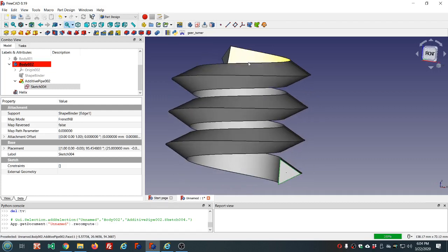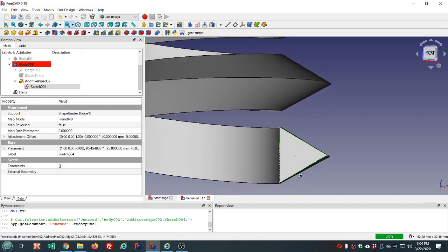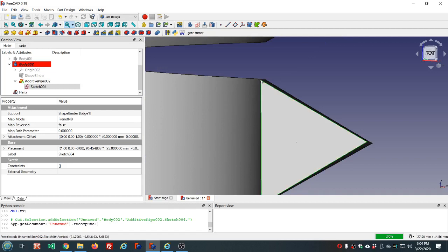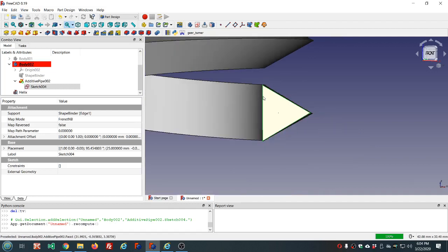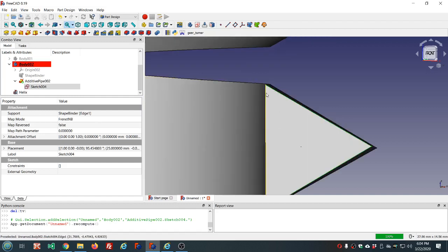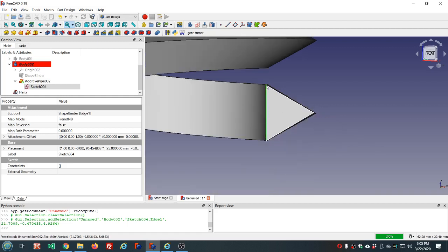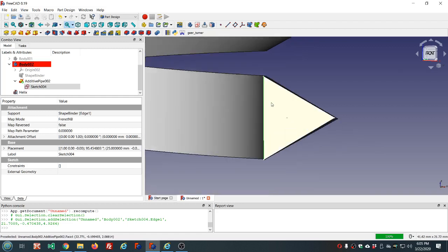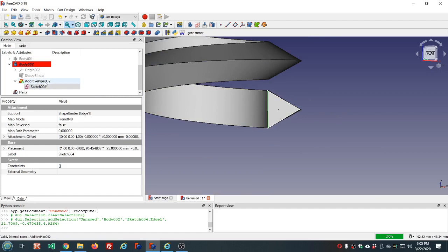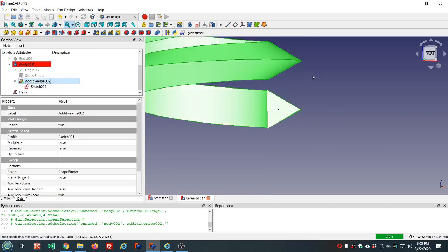So typically you would make it just a little bit smaller than the pitch. So if you're doing a pitch of 1.0, maybe you would do 0.99 or something as your height. If you're getting a self-intersection.